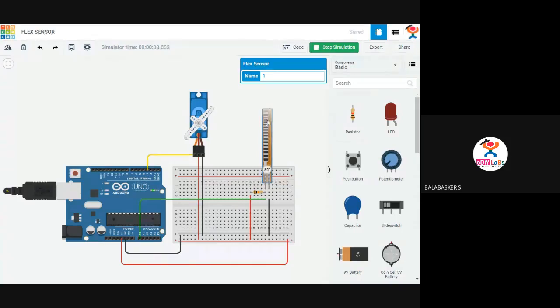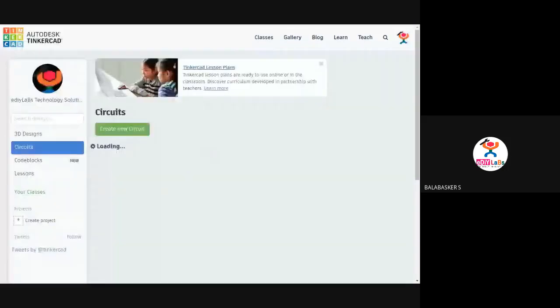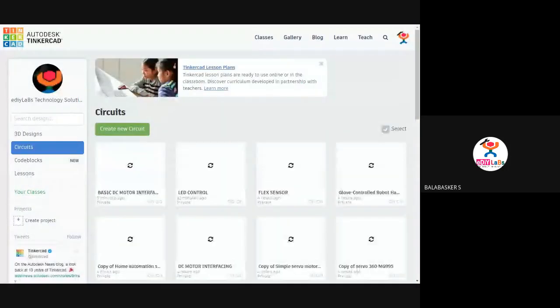Instead of a flex sensor, you can just keep your finger. You can take the center finger or some other finger. You will be moving it, and that movement will be controlled. So if I move that finger, the corresponding servo motor's angle will be changed, and based upon that, the corresponding value will be moved. That is what happens. This is a single finger. Right now I'm moving to multiple fingers. I'm showing 5 fingers. So 5 fingers means you need 5 servo motors and 5 flex sensors.